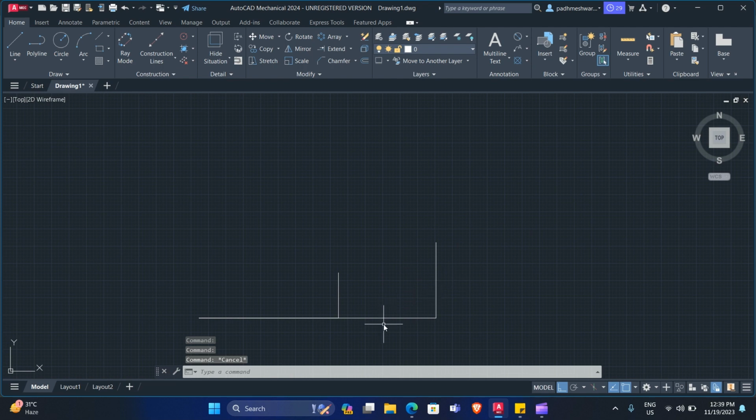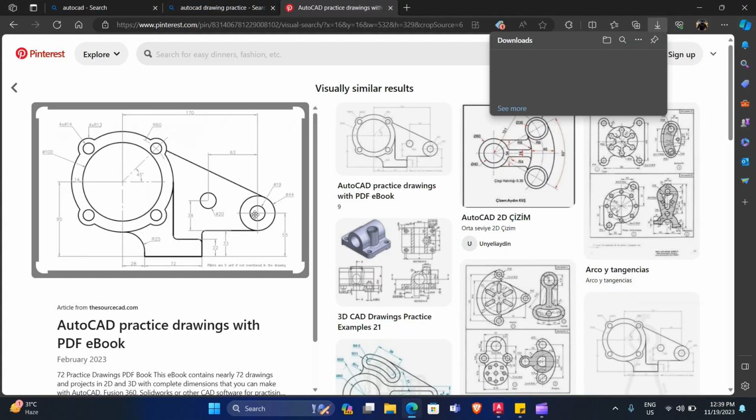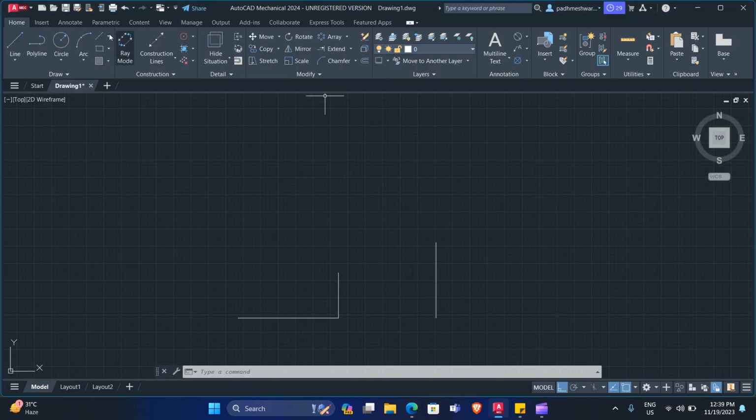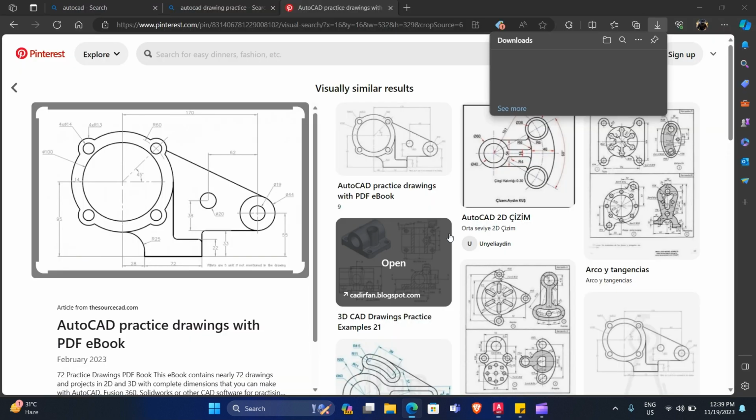As you know, this line was not on the drawing, so we are deleting it. And this line was also not on the drawing, so we are deleting it. And here at this point, what is there? A circle, for diameter 19 and diameter 44. We can go here and select circle or click C and enter. Just go to the point and click that point, and this is 44 and 19.